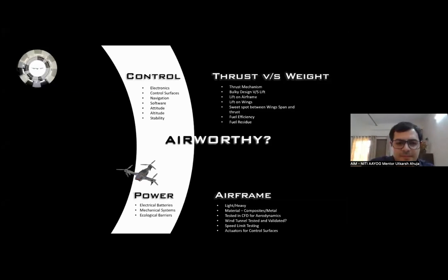Yeah. In case of power, right? I'm just trying to demonstrate to you. So let's suppose this drone is flying. That's wherein the drone is having stability. It's a tricopter. In this case, the drone is having stability. If I increase the power of the motors, the drone will be able to fly upward. Why? Because it has increased its thrust. But at the same time, it has to balance all those air gusts which have been created. So this balancing left and right, forward and backward is done by a controller called a PID controller.